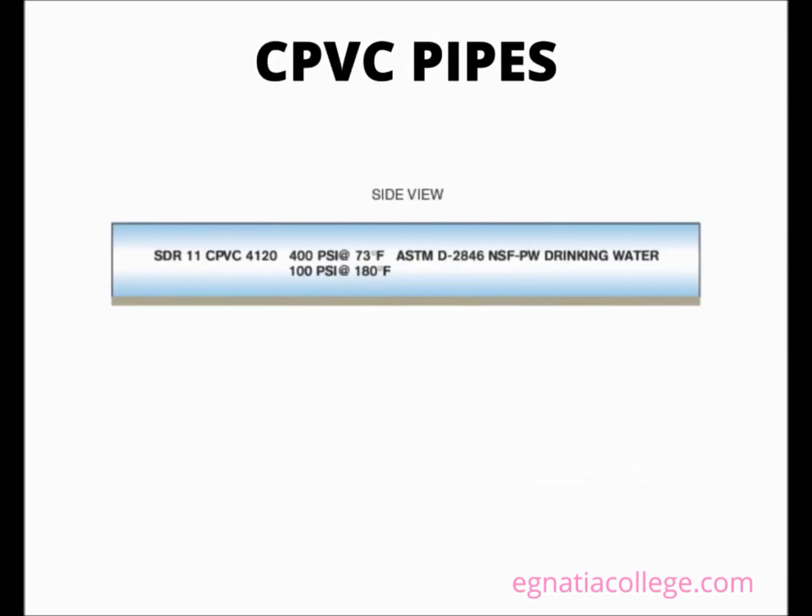CPVC pipe. Chlorinated polyvinyl chloride pipe, CPVC, is flexible, but is typically called pipe and not tubing. It is a yellowish-white material joined with a solvent weld process, glue used. The higher the temperature of the water, the lower the pressure rating of the pipe. As with all plastic piping, CPVC expands and contracts based on the water temperature. Long-term exposure to UV rays may damage CPVC.